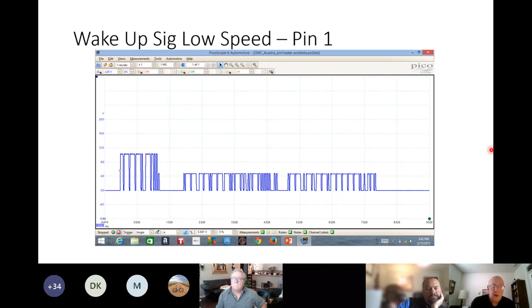On many of the GMs, you get an exaggerated low speed, which you see right over here. And that exaggerated low speed allows you to set, see the gold square? So what I've done is I've set my trigger slightly higher than the actual packet of information we'll be running. Because it's slightly higher, then I can set the oscilloscope up for a single transfer of one pattern all the way across the screen, and you'll have nothing on the screen until you achieve the conditions that have been set by trigger. And then once trigger occurs.